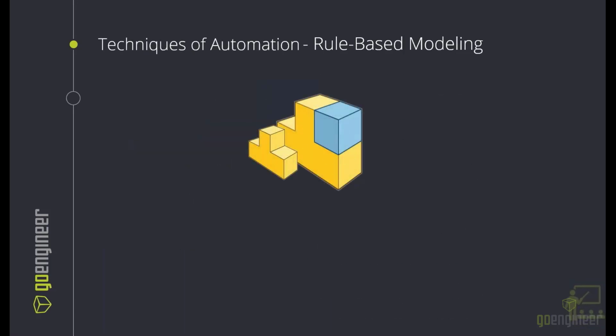So, four techniques of automation, the first one being rule-based modeling. I think this is maybe what we're familiar with when we think of any sort of interdependencies between dimensions. This could be where one dimension is equal to another dimension or is equal to half of that dimension, or it could be things like if statements, where if a value is 0, then we'll suppress these parts or we'll unsuppress them based on whatever it is.